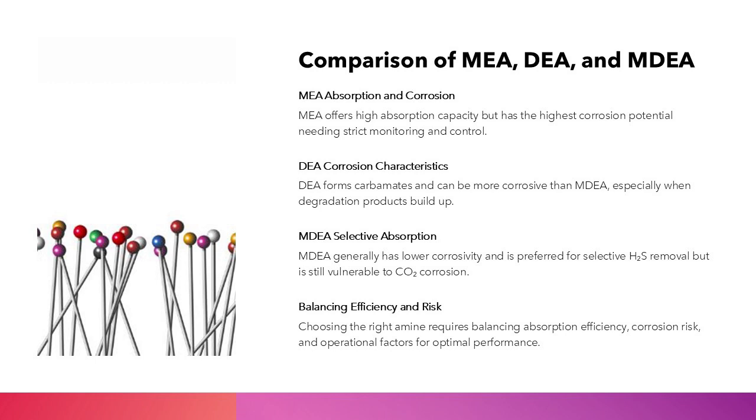MDEA, a tertiary amine, generally has lower intrinsic corrosivity and is preferred for selective H2S removal, but it remains susceptible to corrosion when CO2 is present. Understanding these differences is vital for selecting the appropriate amine for specific applications and implementing tailored corrosion control strategies. Operators must balance absorption efficiency, corrosion risk, and operational constraints to optimize system performance.